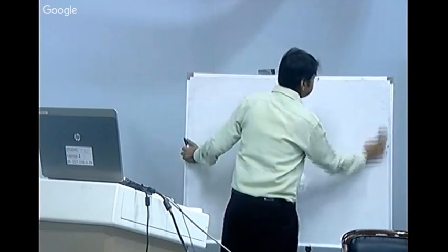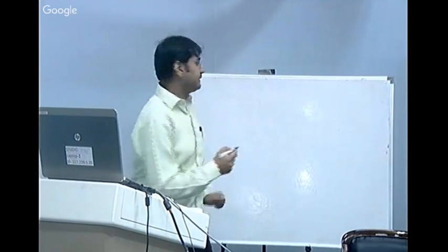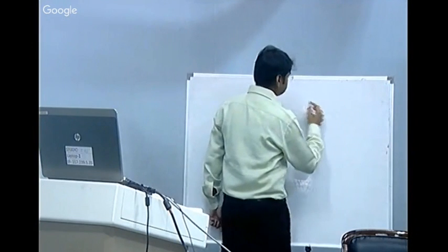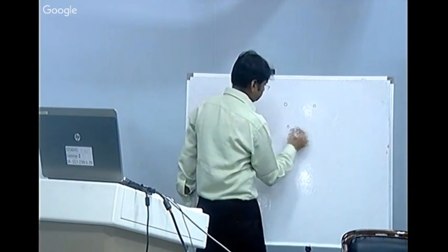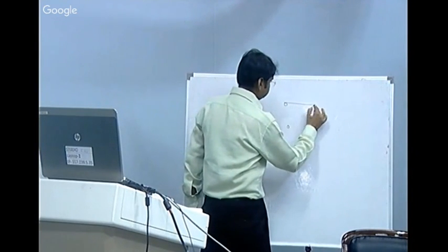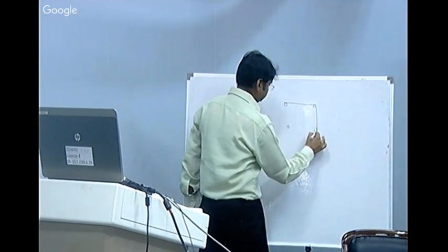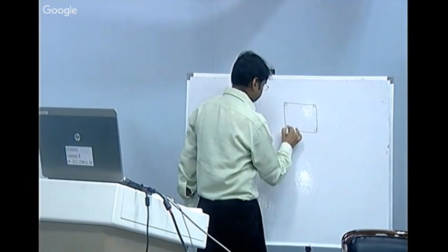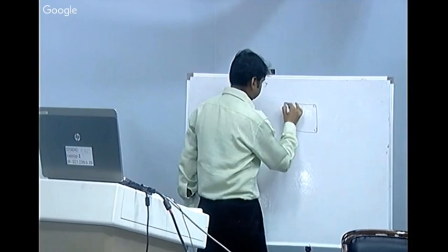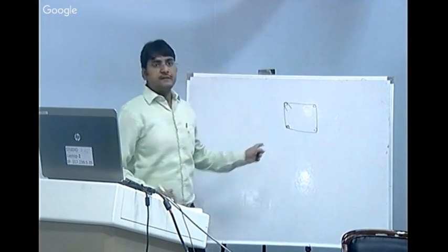What do you mean by stirrups? The function of stirrups is number 1, to keep the main reinforcement in position during any earthquake. These are the stirrups. You have seen the rings.